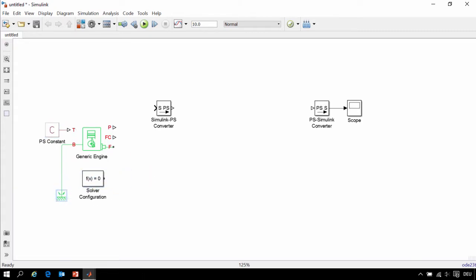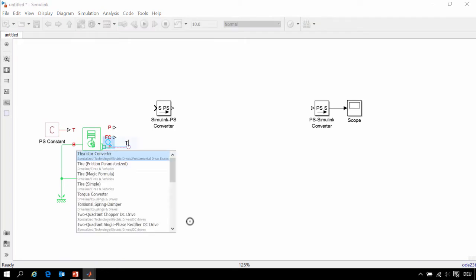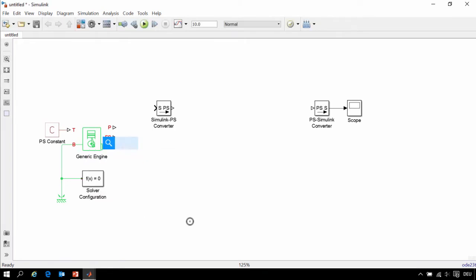Simscape and Simscape Driveline use solver technology above and beyond what is available in normal Simulink. To have access to those settings, we'll attach the solver configuration block. This mechanical connection goes to the rest of the drivetrain. The first component in our drivetrain is the torque converter. We'll attach that here. Next, we'll attach an inertia that represents the inertia of the remainder of the drivetrain.